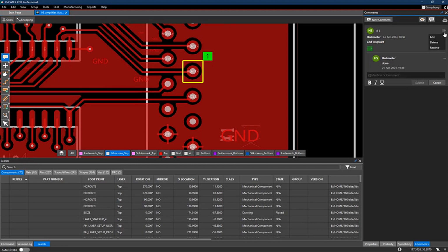And then for sure you can get rid of this stuff. You can archive it. This is also sometimes useful when you give a board to a subcontractor. You can archive all this, then load it again into your board to see whether the subcontractor's layout has really done its job in the way you want. Good, so much about this markup.